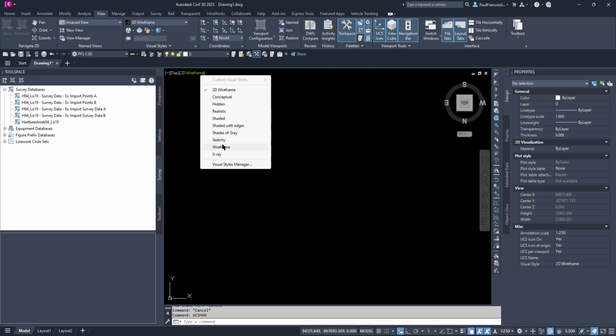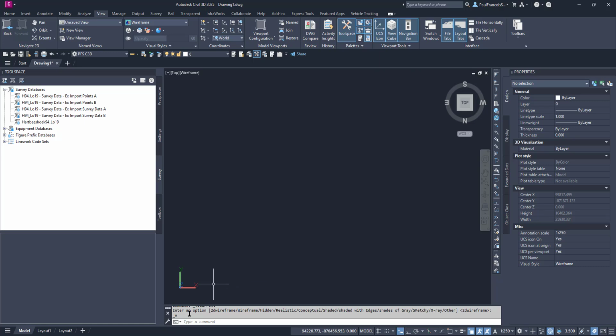And if you switch out to a 3D view like a wireframe instead of a 2D wireframe, you can see Y is pointing south, X is pointing west, exactly according to the South African convention. We just swap X and Y. But anyway, let's not get caught in the complexities of the South African coordinate system. Let's just fix on exactly what we need to do to get our project up and running.